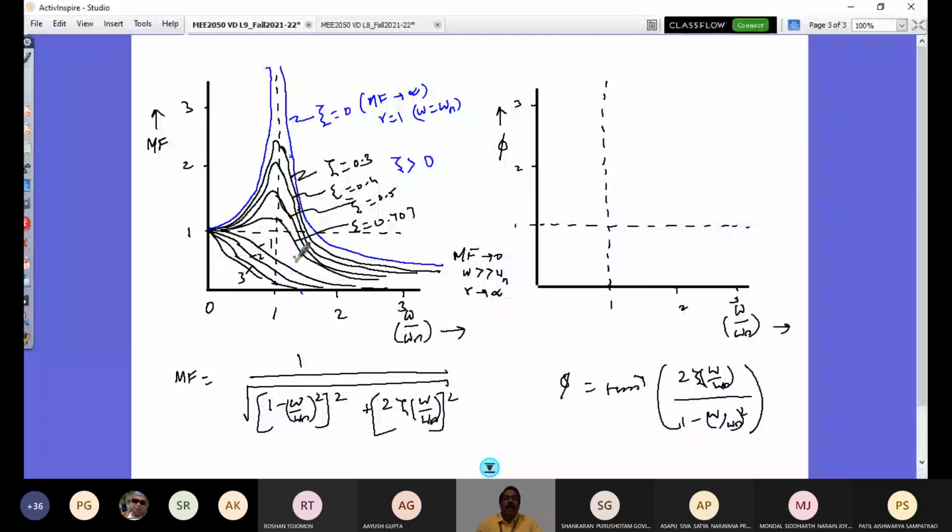Of course, the rotation should cross that, and that is what is called a critical speed, and that would be quickly crossed. The damping present in the system would take care that the amplitude in the shaft is very small when it is crossing, and then the operating speeds are so high that it won't be a problem at all for smooth generation of power. So this is all something that you understand from this graph.